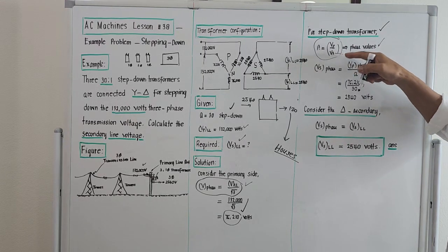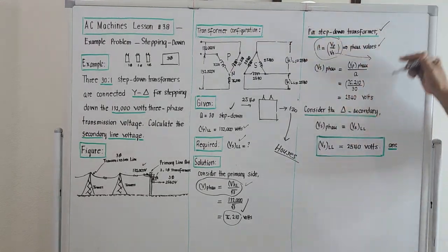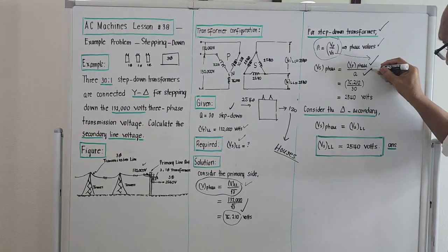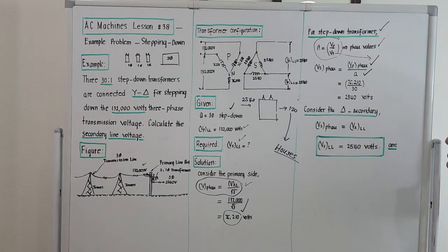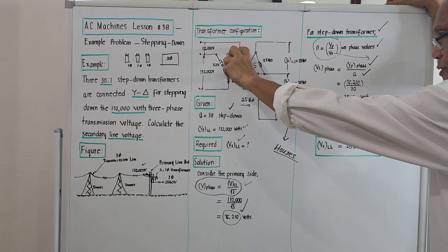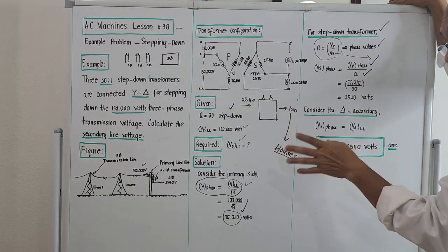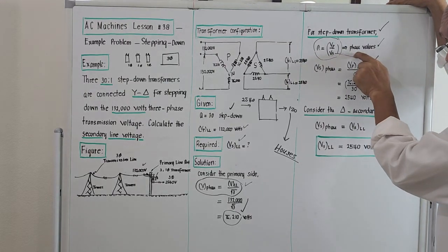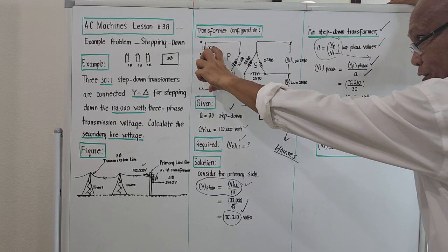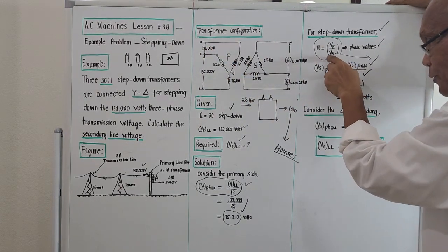Vs now, okay, we put this here, and A will be underneath. So this should be the phase voltage on the primary all over A. To get this value here, we will take this value and divide it by the ratio of transformation, considering phase values. The emphasis is on the phase value. It's not this value here. It should be the phase value, divided by the ratio of transformation.